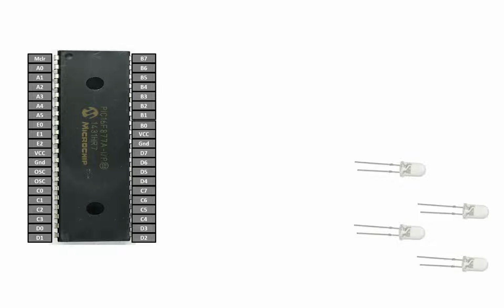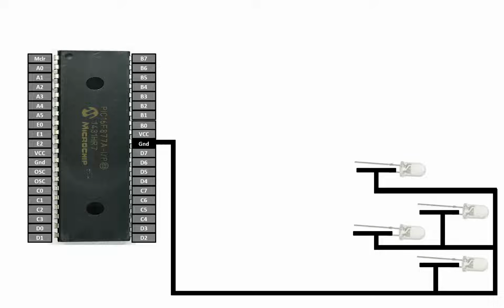Now guys, let me show you how to connect this LED with a PIC so we can move on to the programming. Now as you can see, each LED has 2 pins, one longer and one shorter. The shorter pin, I make it black like this, and shorter pin is always the ground, while the longer pin is always the power of the LED, and you cannot shuffle these 2 pins. Now for the shorter pins, as you know, these are ground pins. Now I common them and send them to the common ground of the PIC16F877A microcontroller like this.